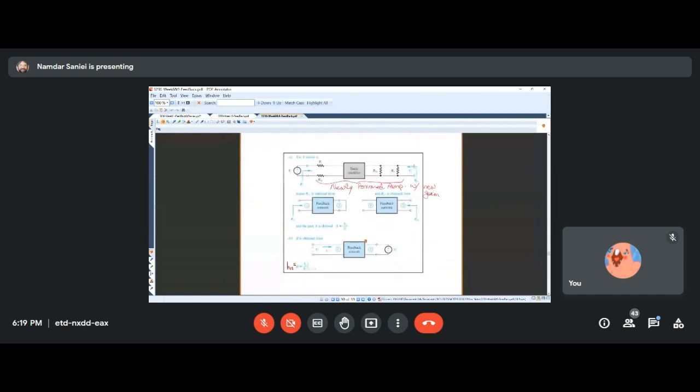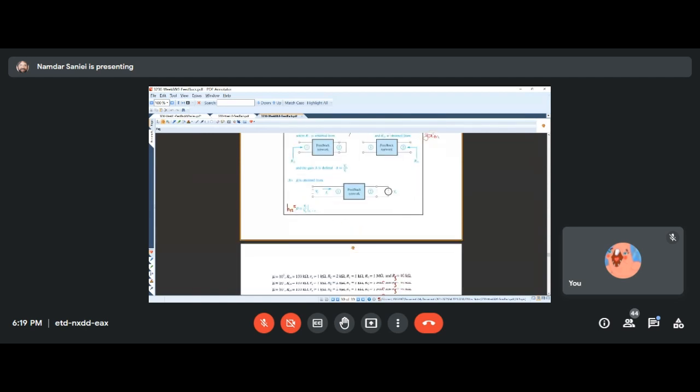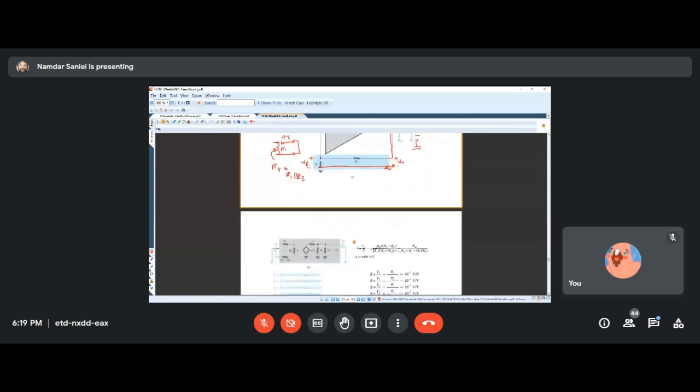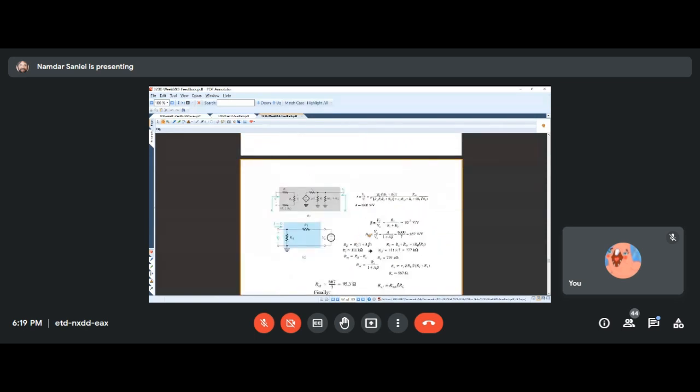So basically, in all these cases, we end up absorbing the extra resistances into the amplifier so that the feedback network is ideal, and then it's attached to an amplifier, and therefore it looks like the ideal situation. Finding the gain of the amplifier and finding beta properly, then we could use the formula AF equals A over 1 plus A beta.